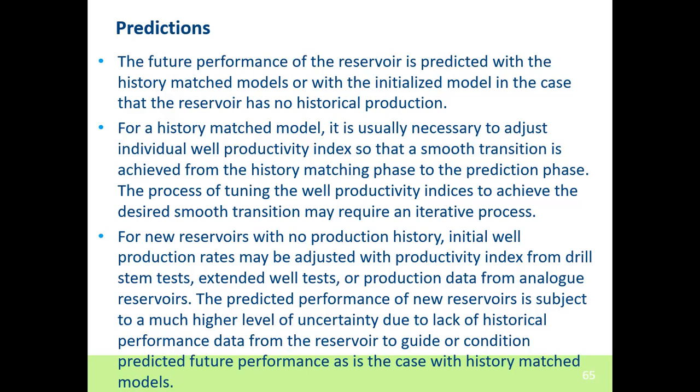For new reservoirs with little or no production history, initial well production rates may be adjusted using productivity index from a drill stem test or extended well test. For new reservoirs, it's impractical to carry out any form of history matching.